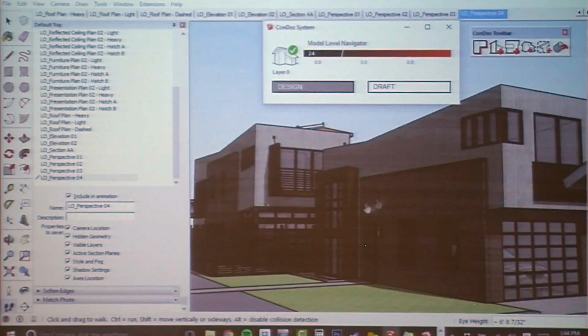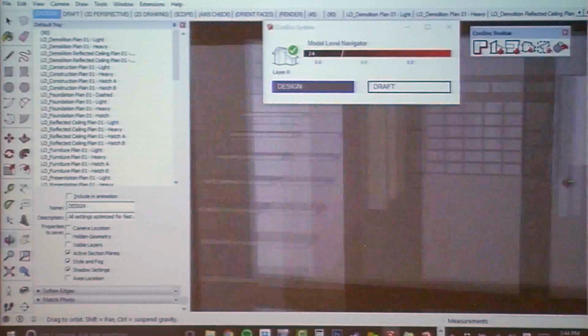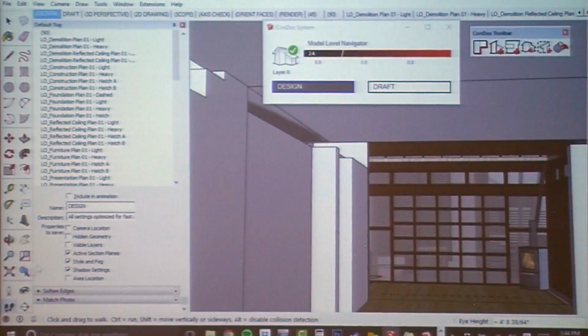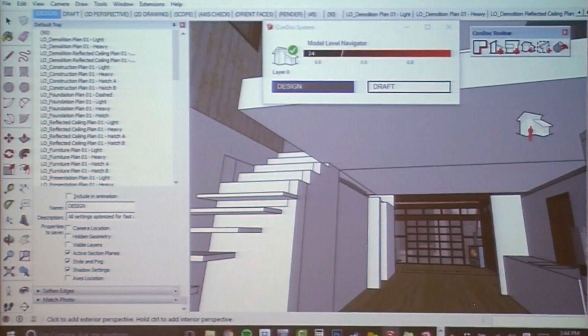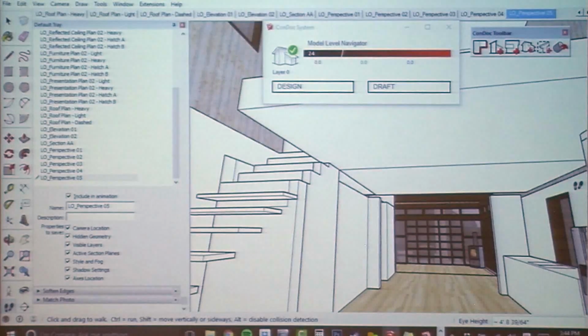Okay, and then it's not to say either that if you were to go to the inside, I don't know if you guys have ever added a section or a perspective view on the inside of a SketchUp model, but oftentimes your ceilings end up pretty gray. So with the perspective tool, if I hold Control, the little guy jumps in the house, and now when I add a perspective, everything is optimized for interior perspectives in SketchUp.